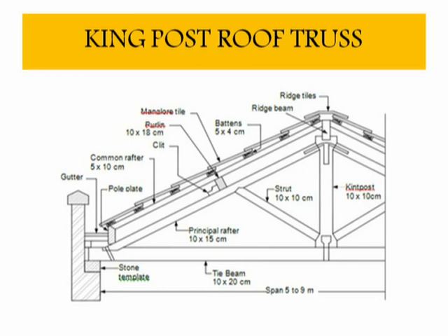The inclined member is known as the strut. At the bottom you can see the beam. The purlins are provided, and the different roofing tiles are provided. Normally it is Mangalore tile roofing. To support that, the rafters and the purlins are provided. At the top of the tiles is what is known as a ridge tile.